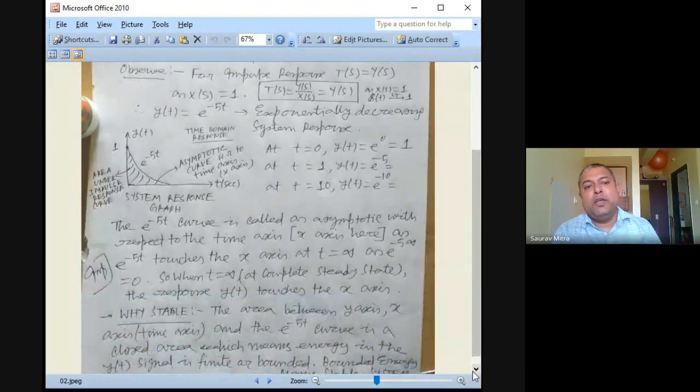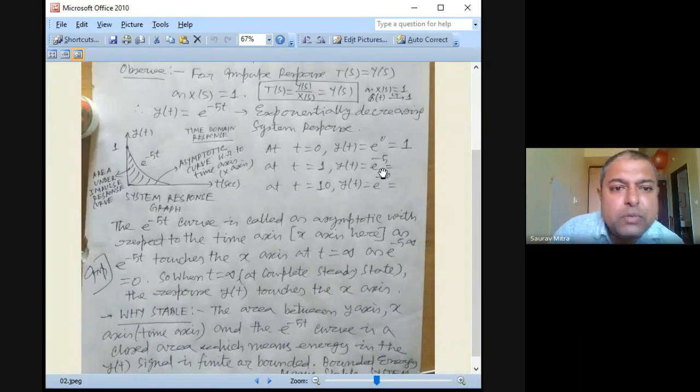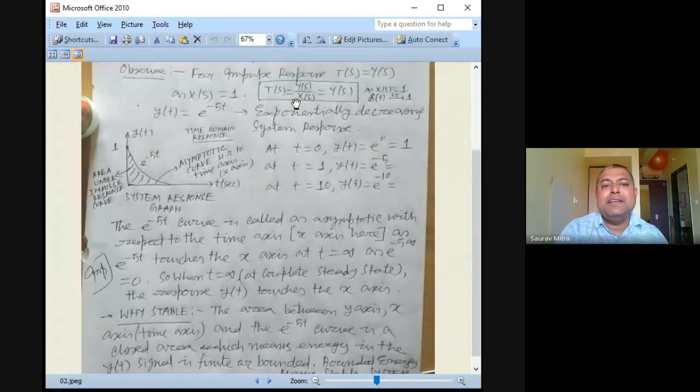Now observe, for impulse response T(s) equal to Y(s) because X(s) is equal to 1. So T(s) equal to Y(s) by X(s), as X(s) is equal to 1, T(s) equal to Y(s). Why am I telling you all this? Because it is my experience which tells me it's a very simple thing, but students cannot understand it because in no book it is written so clearly. It's a very simple fundamental that T(s) is equal to Y(s) by X(s). X(s) is nothing but the Laplace of the impulse.